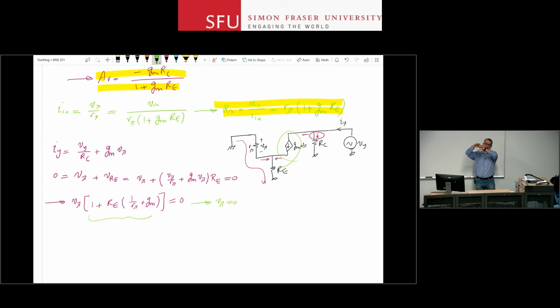The current source here is a function of something else in your circuit. So basically, you have separated V out from the input side of your circuit by having a current source in between them. But what that means is that it turns out that the current source is also 0 because V pi is 0.